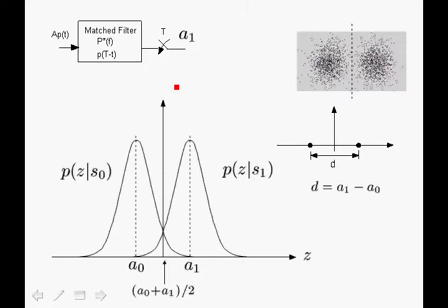Now this is a very important diagram. Here we show the actual symbols that are sent in a constellation diagram, but basically this is the symbol corresponding to A0, and this is the symbol corresponding to A1. At the receiver, we receive these signals with additive noise effects, so that the signals that we actually receive will not be at the ideal point, but would be scattered about.